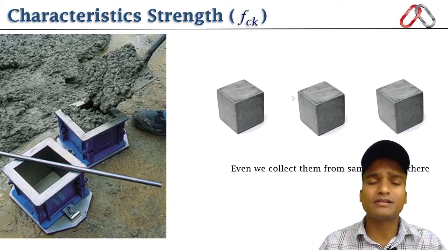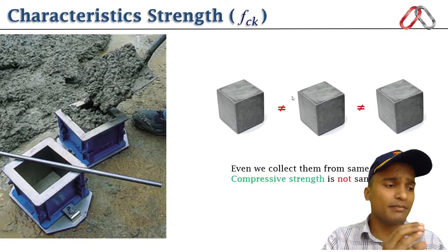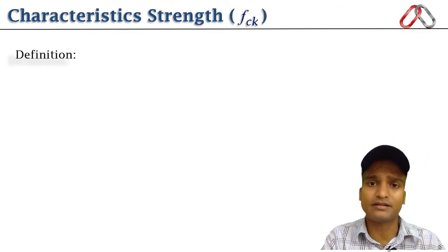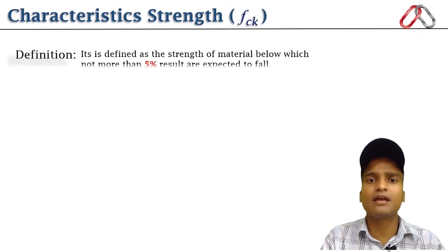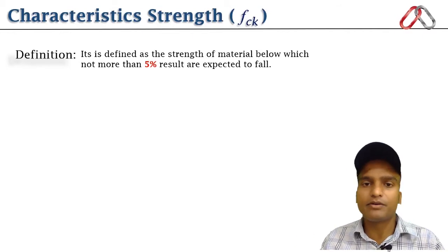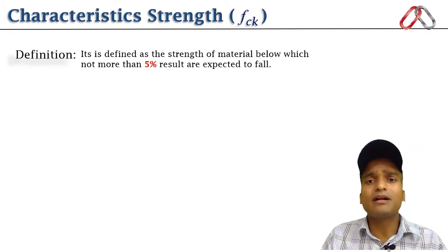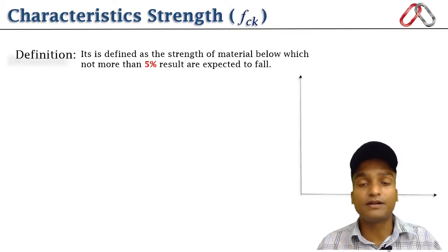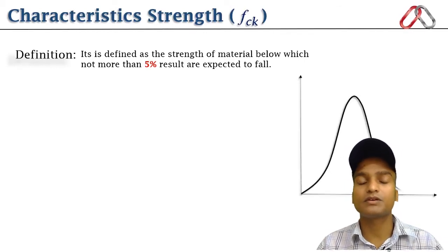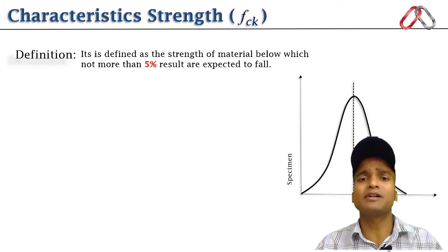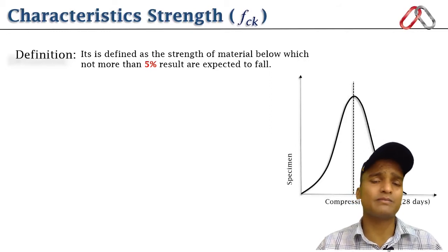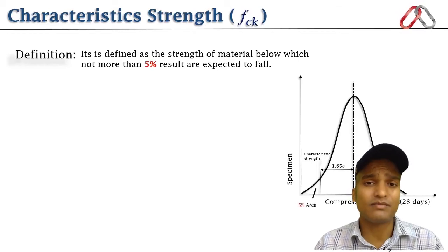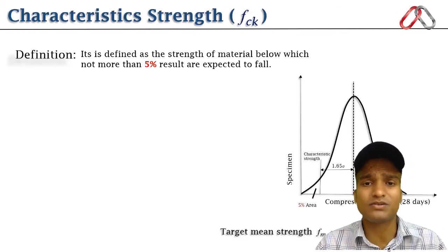The most interesting phenomenon is that when we make different molds from the same concrete that we have cast in the same condition, and if we test them in the laboratory, we get different values of compressive strength, and the data is completely scattered on the graph. That's why we have discussed the characteristic strength curve and why we choose only characteristic strength.